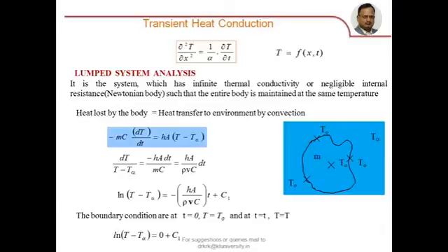That is the secret involved in this. I am ruling out the temperature dependence on X because temperature at any point X remains the same. So I am simplifying this problem by making the temperature independent of X and only depending on the time.